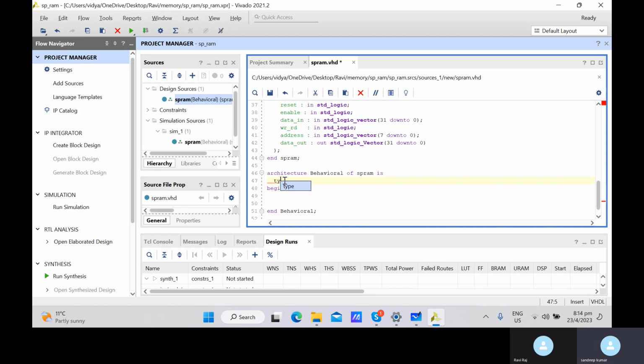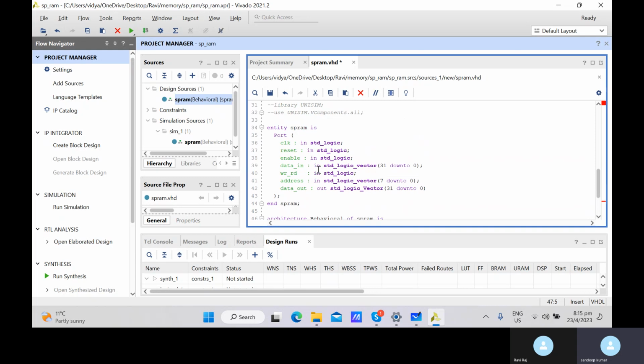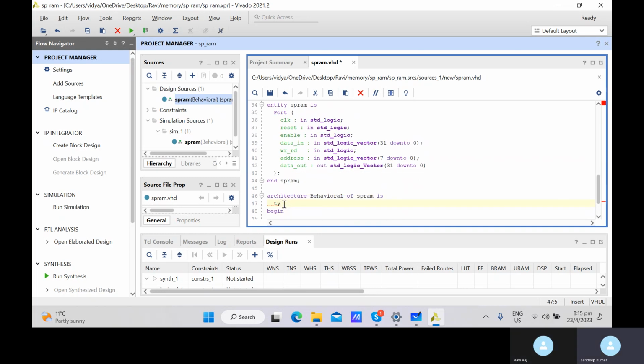In ASIC, memories are hard macros, basically, generated by the memory vendors, and they provide you the tool from which you can generate the memory, and you just instantiate the memory and use it. You don't write the code for memory in the ASIC. Understand? This kind of memory will already be available with similar ports, and you just use it in the ASIC. But in FPGA, you definitely have to code it to infer what kind of memory you want from the FPGA.